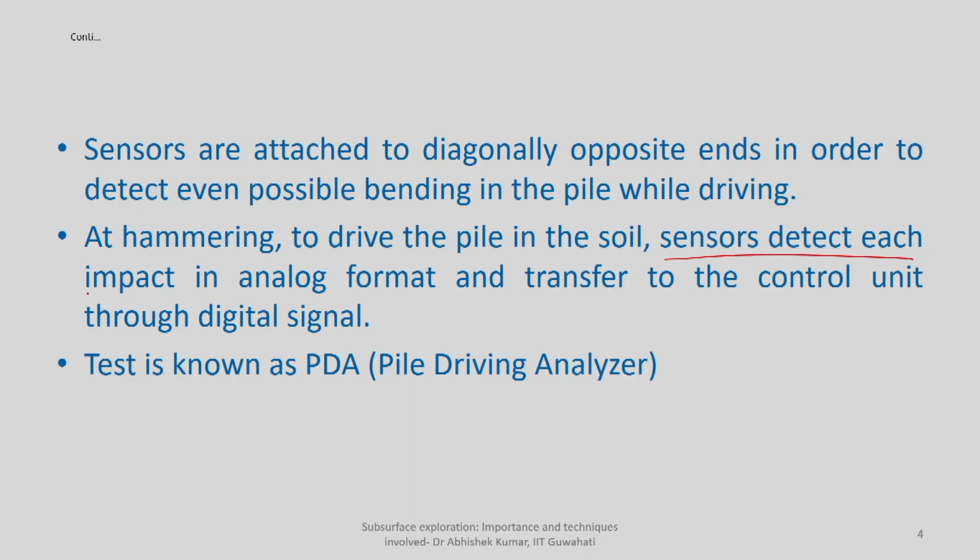As you hammer, the pile will be pushed into the ground and the sensors will detect any resistance offered by the pile medium at different depths. Collectively, the resistance finally offered by the soil to the pile will be the resistance offered by the pile to the external loading. The sensors detect these things in analog format, which is sent to the control unit or PDA unit in terms of digital signal. The test is known as PDA, Pile Driving Analyzer.